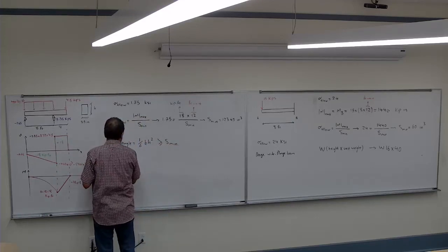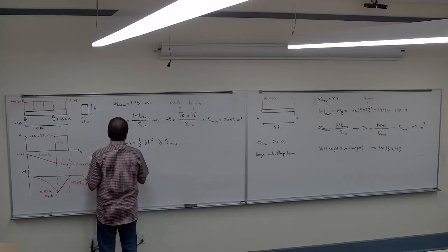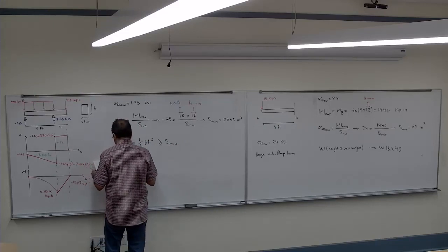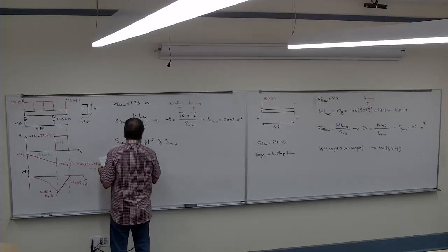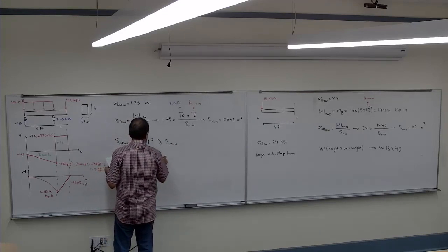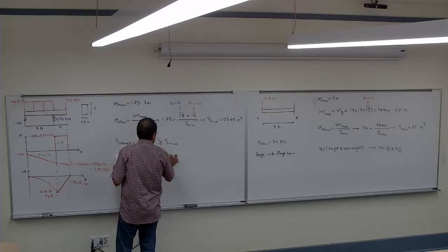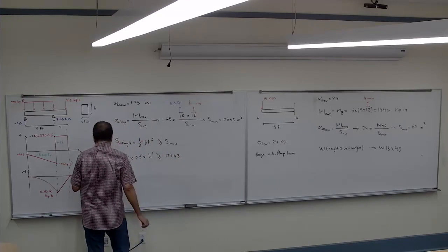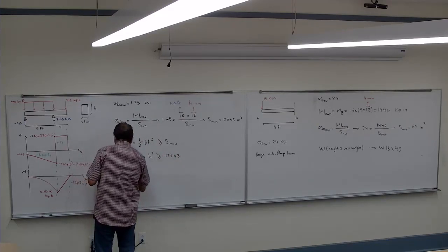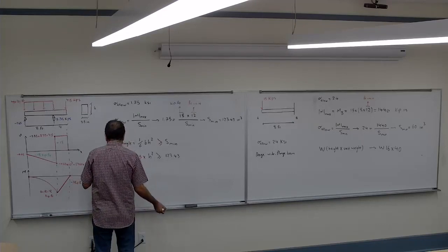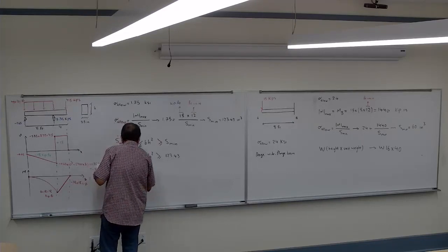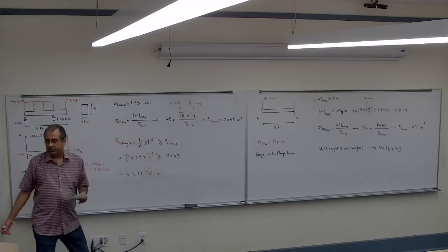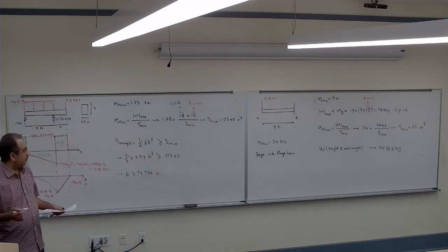So therefore, 1/6 of the B, which is 3.5 inch, multiplied by the H squared should be larger or equal to 123.43. So therefore the H should be equal or larger than 14.546 inch. So the H I'm choosing should be larger than that number.